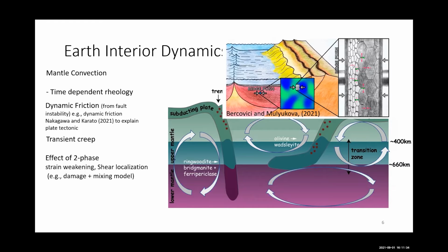But because of the secondary phase, the grain size will be small, and grain growth will be inhibited by the secondary phase, which would act as a pinning agent. And so you would remain locally, at least, in this fine-grain, grain-size-sensitive deformation regime, which is a lot weaker than the large-grain or dislocation creep regime, and would potentially weaken the aggregate.